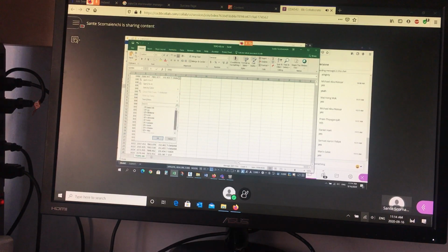So there are descriptions called TCL, T in bank, TEOP. The T stands for topographical point, and then dash whatever it is, what the point represents. So this is the center line. It doesn't have to be a road. It could be a center line of a ditch and so on. So there's so many different things.